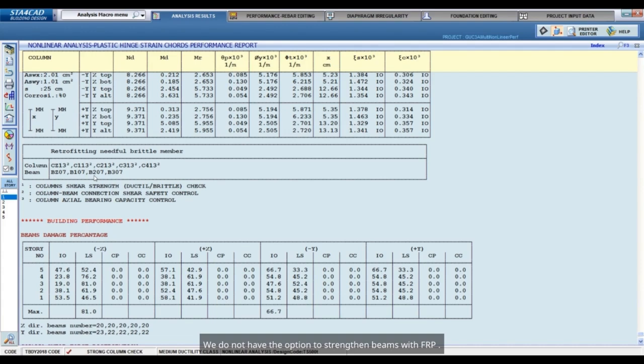When such situations occur in beams, we can add strengthening walls, thereby transferring the excess load from the beams to these walls, because the most effective elements during an earthquake are the rigid walls. When we add strengthening panels to the strengthening wall, these panels will absorb the effects on these elements. In this way, we can prevent the beams from being overloaded.